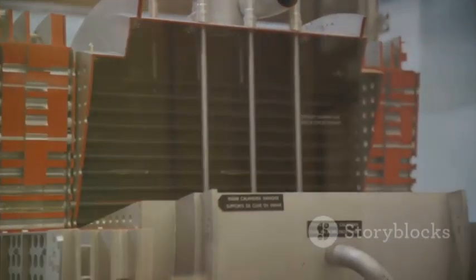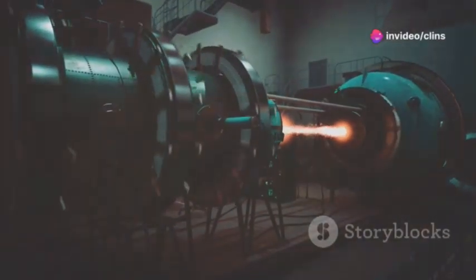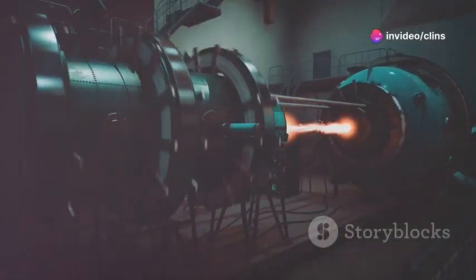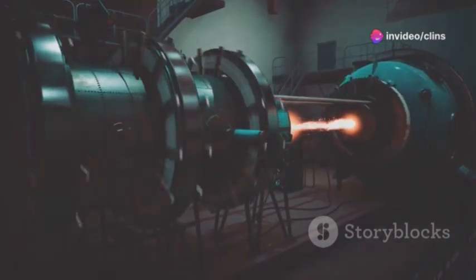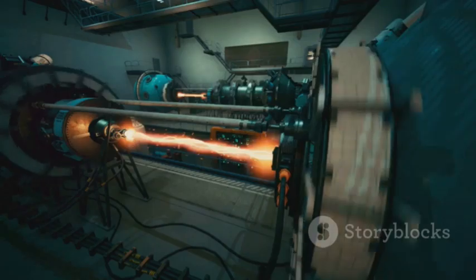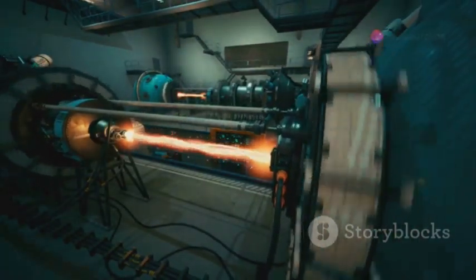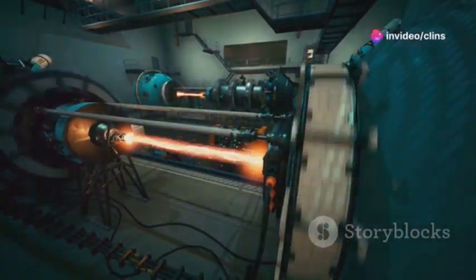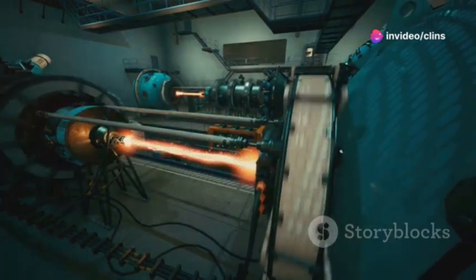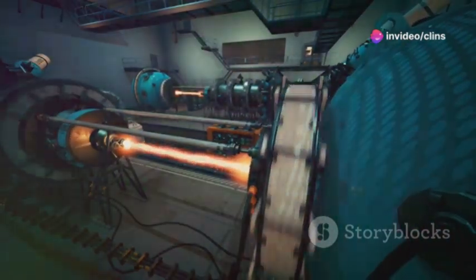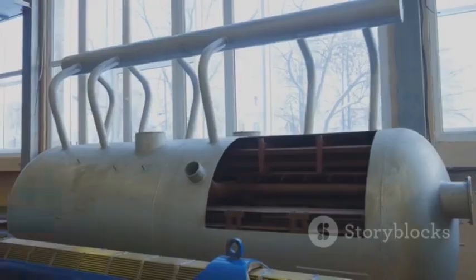Fast breeder reactor, often abbreviated as FBR. The principle behind this type of reactor is the use of fast neutrons and a mixed oxide fuel, usually comprising uranium and plutonium. This combination generates more fissile material than it consumes. Interestingly, the process does not involve a moderator, and the coolant is often a liquid metal like sodium, which ensures efficient heat transfer.